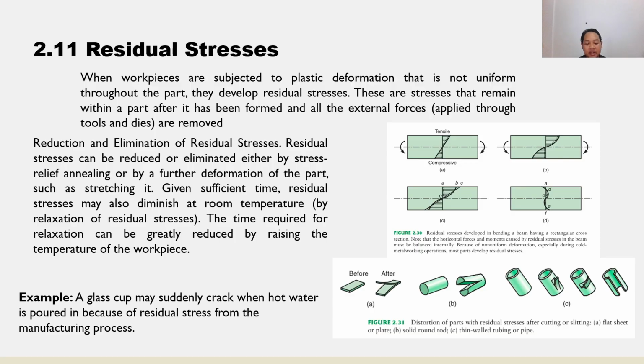They can have both beneficial and detrimental effects. While compressive residual stress may improve fatigue resistance, tensile residual stress can cause distortion or even premature failure. Managing residual stress is a key aspect of ensuring product reliability in manufacturing. The example of residual stress is a glass cup may suddenly crack when hot water is poured in because of residual stress from the manufacturing process.